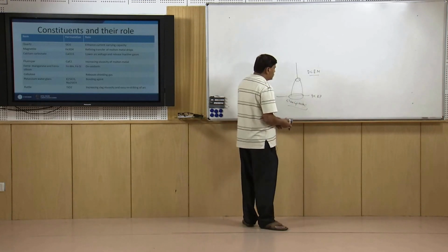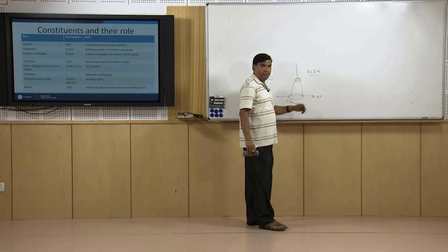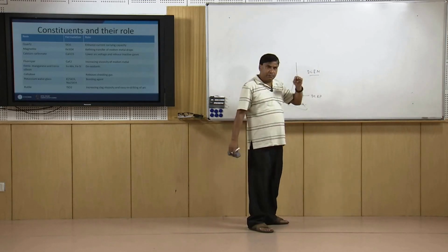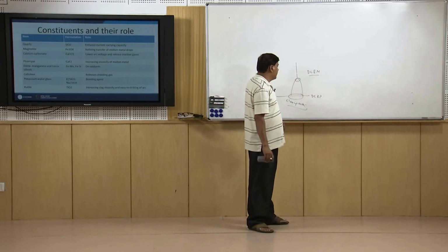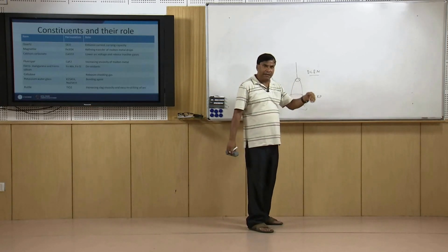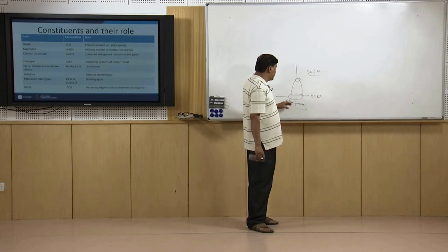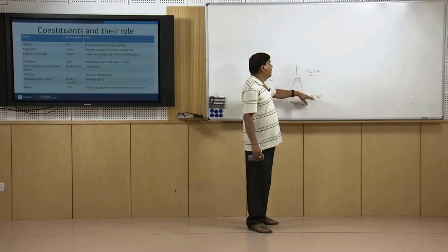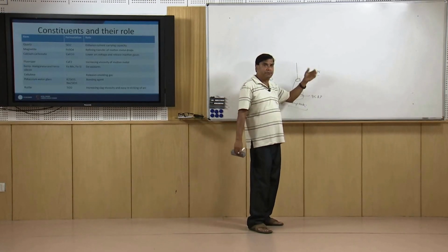So, these are two contradicting requirements. We want that less heat is generated for a much better life of the electrode. At the same time, when aluminum and magnesium are welded, the cleaning action is also required, but these two can be achieved using two different types of polarities.